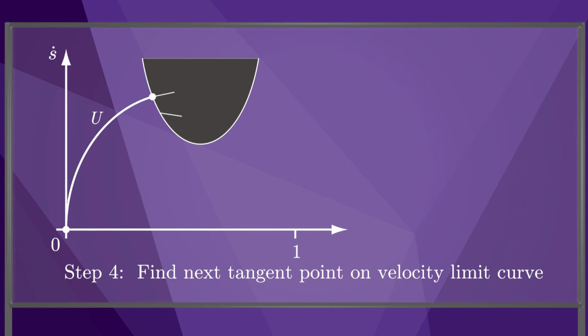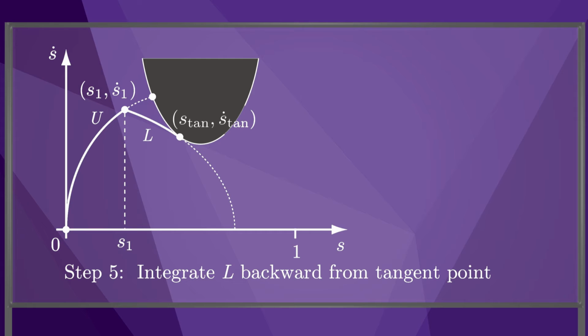As we search along the velocity limit curve, we eventually find a point on the curve where the motion ray is tangent to the limit curve. We can now proceed with the algorithm as before. There are some other technical details, special cases, and improvements to the algorithm, some described in the book, but the description I've given covers the most important points.